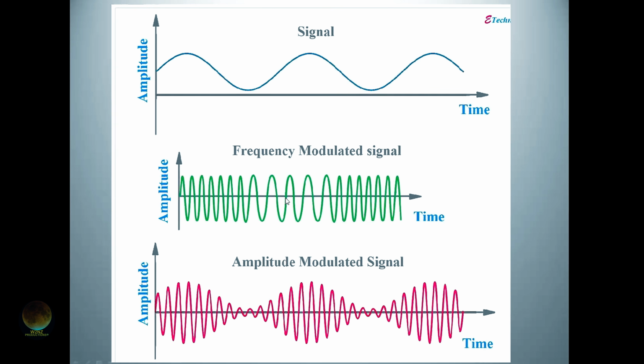Notice, what about the amplitude here? Oh, an FM signal traditionally has a constant amplitude. That's interesting, especially when we get into sound card modes. Now that's true if the modulation audio goes into a single sideband radio, but I'm using a mode like AFSK RTTY. If I look at my power meter on the radio, but my radio's in single sideband, on RTTY it says 50 watts, 50 watts, 50 watts.